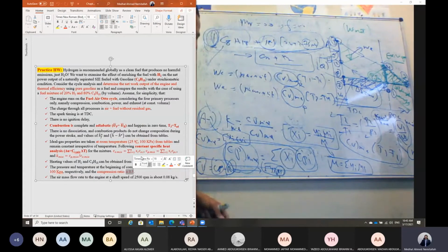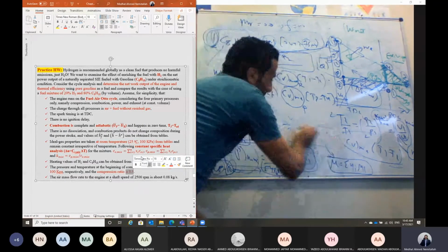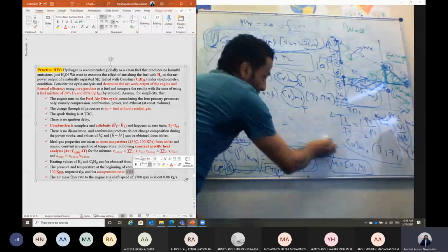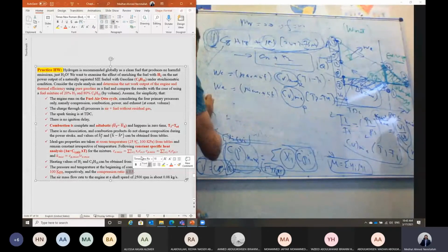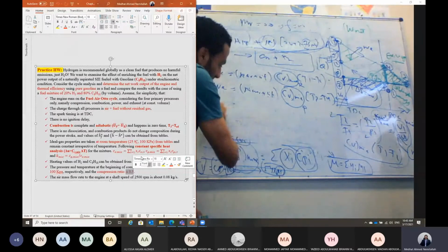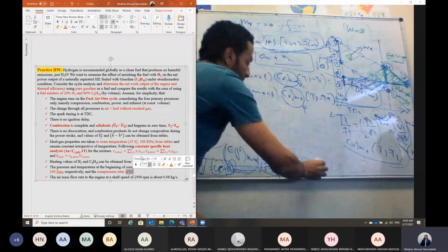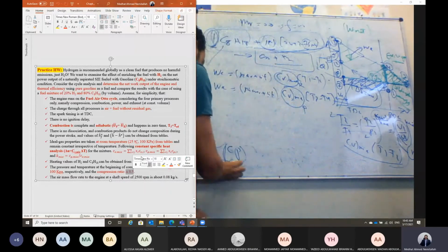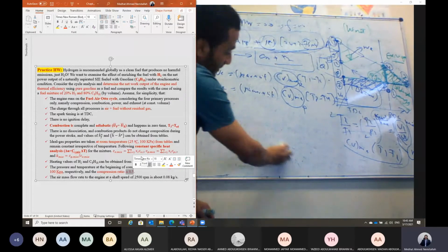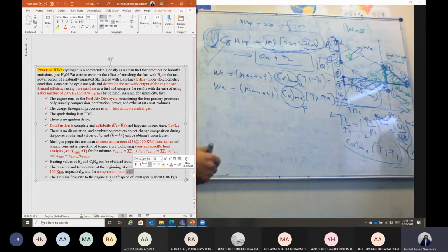And also we can link 3 and 4 similarly to this one. It is isentropic, and also we can get it as a function of the compression ratio. Calculate K for the mixture and CV for the mixture for the product in this case. Then we can calculate the expansion work. Then what about the temperature T3? I need to get the temperature T3.